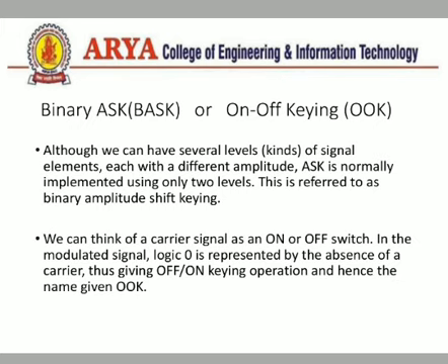This is referred to as binary amplitude shift keying. We can think of a carrier signal as an on or off switch. In the modulated signal, logic 0 is represented by the absence of carrier, thus giving on-off keying operation and hence the name on-off keying.